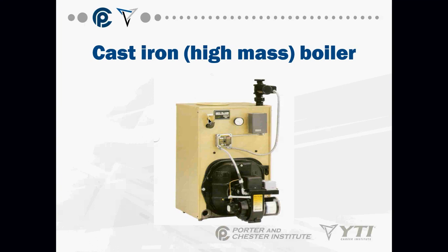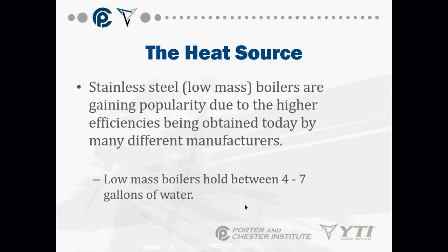So usually when it comes to a boiler, it's a two-man job. 2 guys to bring it in, 2 guys to pipe it. And it's usually done within a day. But that's really it. This little cover right here would actually be for your flue pipe. You would just pop this little cover off, install your flue pipe into the chimney, and obviously do all of your piping connections for your return and your oil line and all that stuff.